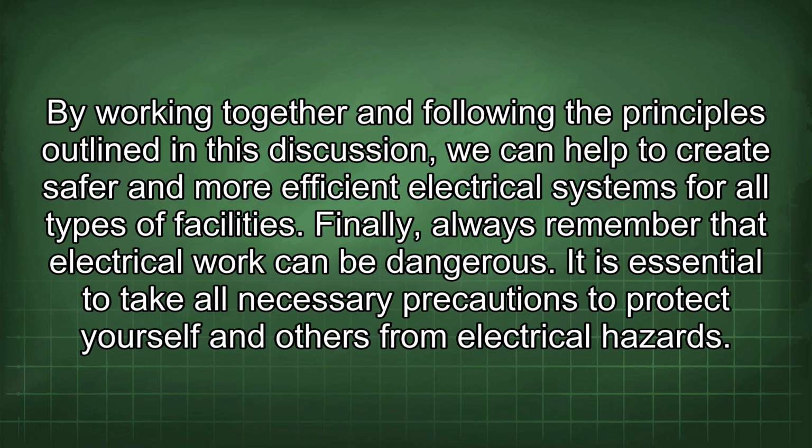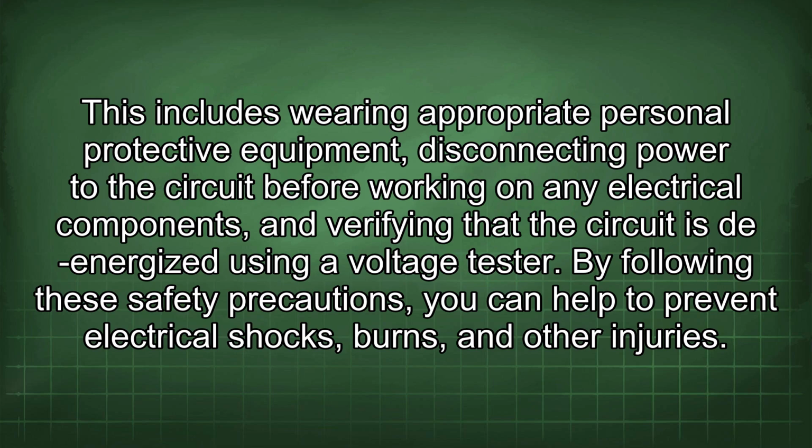By working together and following the principles outlined in this discussion, we can help to create safer and more efficient electrical systems for all types of facilities. Finally, always remember that electrical work can be dangerous. It is essential to take all necessary precautions to protect yourself and others from electrical hazards. This includes wearing appropriate personal protective equipment, disconnecting power to the circuit before working on any electrical components, and verifying that the circuit is de-energized using a voltage tester. By following these safety precautions, you can help to prevent electrical shocks, burns, and other injuries.